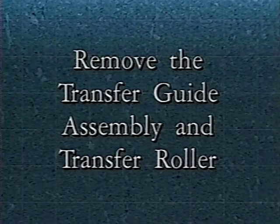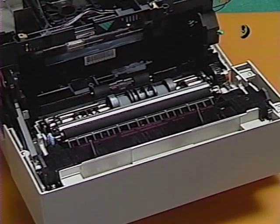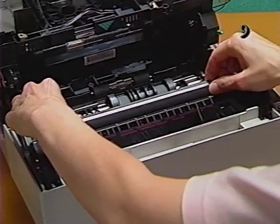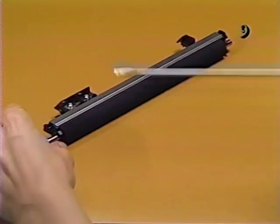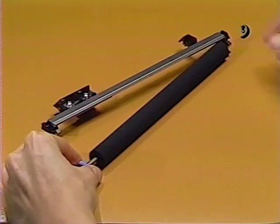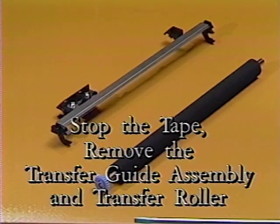Remove the transfer guide assembly and transfer roller. To remove the transfer guide assembly, carefully grasp each end of the assembly and lift it out of the printer. Now remove the transfer roller by using a small flat blade screwdriver to release the transfer roller from the transfer guide assembly. Stop the tape and remove the transfer guide assembly and the transfer roller.